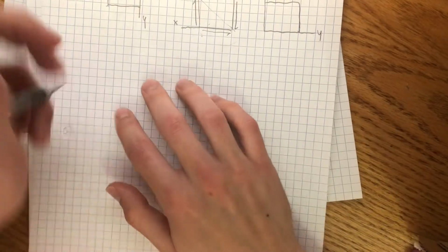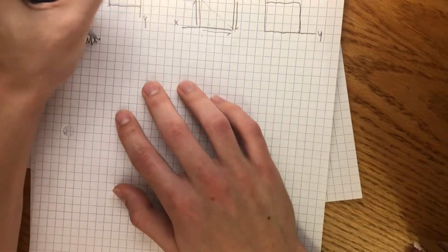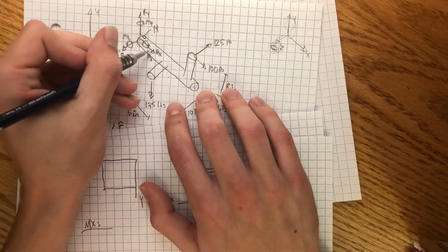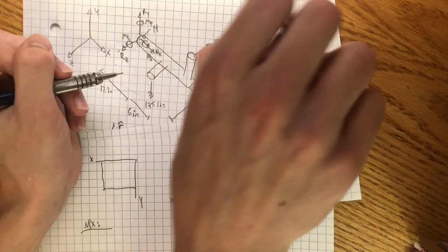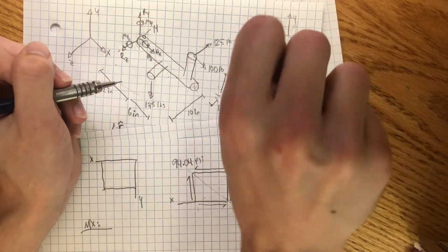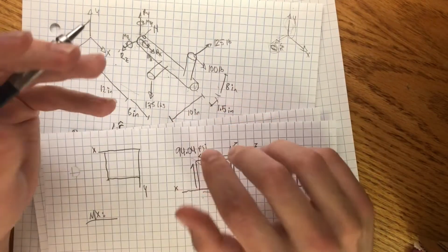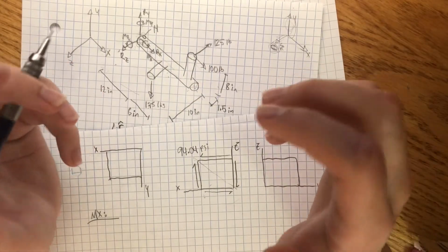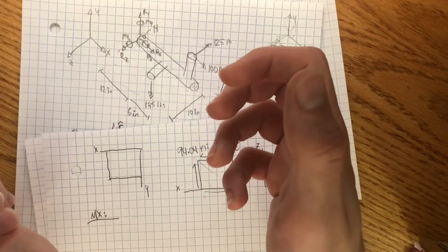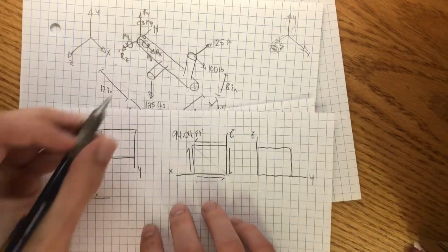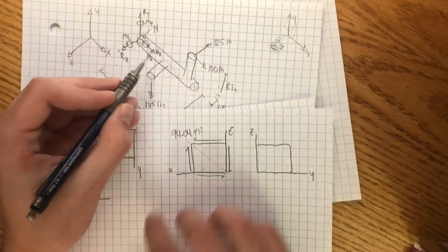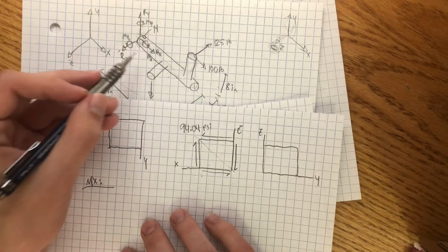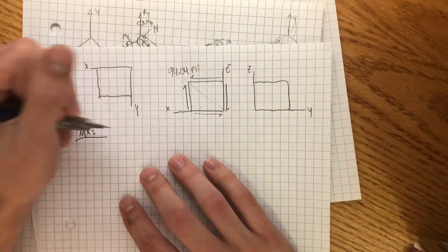So first we're going to start with Mx, the moment about the x-axis. If you look, the moment about the x-axis is as if you grabbed this bar with your hand like this and tried twisting it. That's called torsion. It's as if you were to grab the top and bottom of a soda can with your hands, and turn one hand clockwise and the other hand counterclockwise. You're applying torsion. So Mx here is not going to try and bend it this way or this way. It's just going to try and twist the object. So because of that, we consider Mx to be torsion.